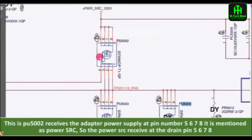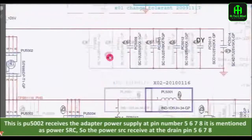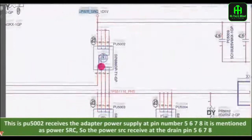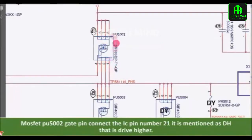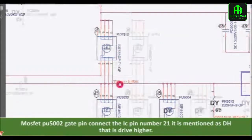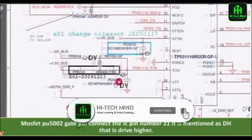PU 5002 receives the adapter power supply at pin number 5, 6, 7 and 8. It is mentioned as power SRC. So the power SRC is received at the drain pins 5, 6, 7 and 8. The MOSFET PU 5002 gate pin connects to IC pin number 21.